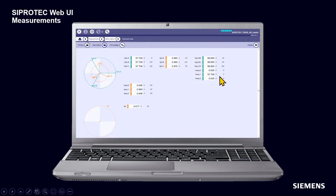Okay, next I can show measurements either in a table form where I see then here the voltages and the currents, phase-to-phase voltages, and the sequences are here shown, so positive, negative sequence and so on. And I can show also here my measured values as phasors in this diagram, as you see here, the voltages and the currents, for example.